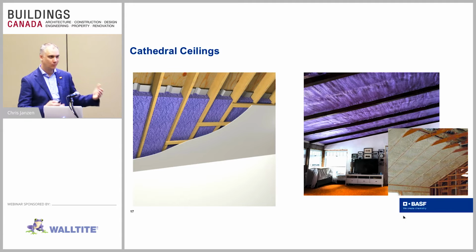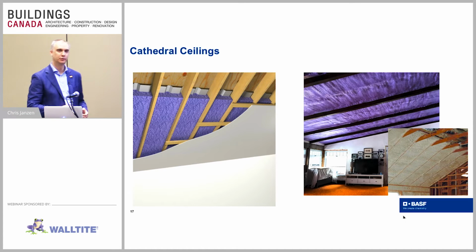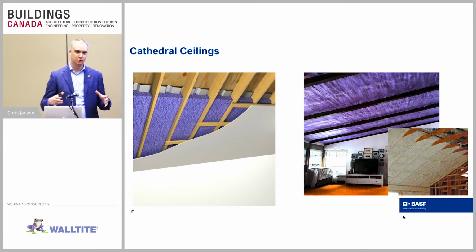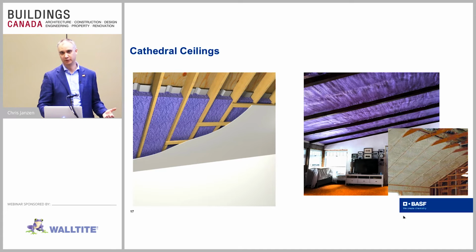One of the things that comes up is that as you're taking stuff apart and maybe adding a second floor onto a house and putting new roofs in, you might be planning to do batt and poly insulation with venting. All of a sudden, as the roof lines come together, you start realizing as a builder that you can't vent this very well, the way the roofs are lining up. So let's just use spray foam, because then we can make it an unvented attic. Again, that's fine, but make sure you get your drawings updated to reflect that.